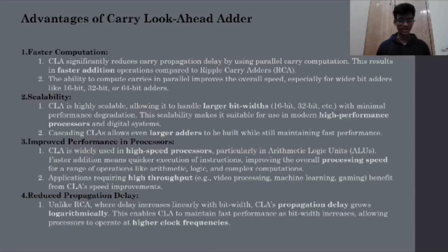Reduced propagation delay. Unlike a ripple carry adder, where delay increases linearly with bit width, CLA propagation delay grows logarithmically. This enables CLA to maintain fast performance as bit width increases, allowing the processor to operate at higher clock frequencies.